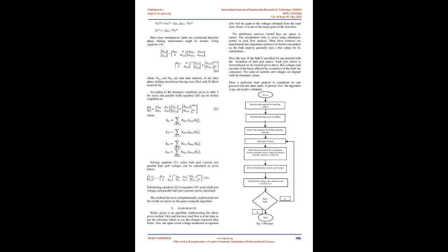Basic network equation, where Z1 and Z2 are known as driving point impedance and Z12 and Z21 are known as transfer impedance. Hence, when a fault occurs anywhere on the system, the impedance matrix changes accordingly. This paper uses the fault port matrix to calculate parameters related to simultaneous faults as given in 4. According to the multiple port theory, each fault point is considered as a port. In a port, the current coming out of one terminal should be equal to the current entering another terminal.